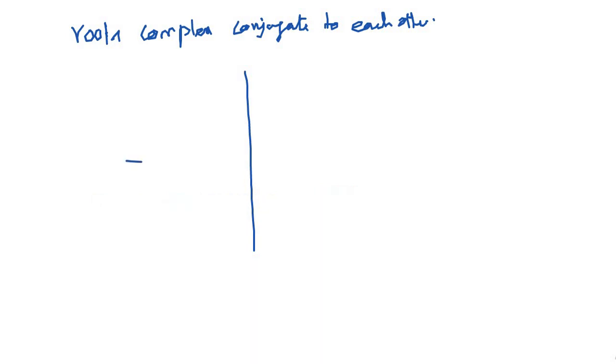Real part can also be positive if zeta is a fraction with a negative value. That is also possible, but we will not concentrate more on those kinds of systems, but still we'll solve problems related to that. So you will have two roots. Those two roots are having negative real part in our case, that is minus zeta times omega n. Then they are having imaginary parts that are equal and opposite.